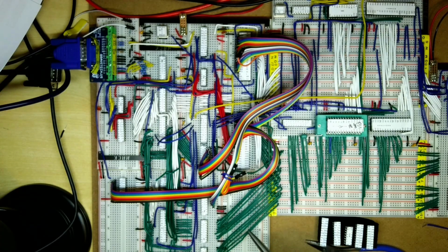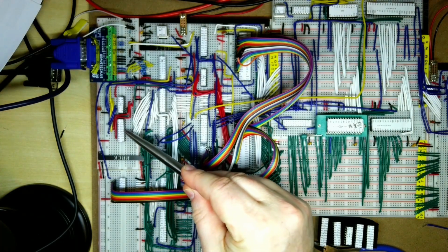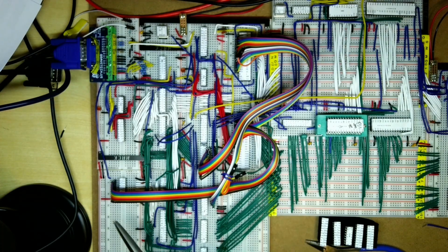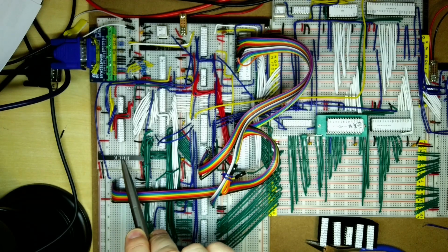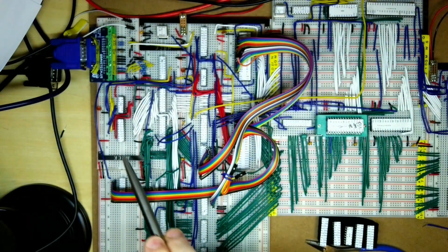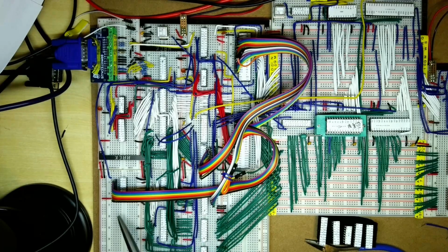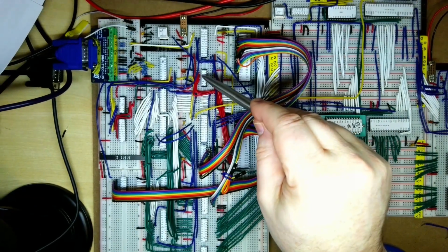So we may need to reroute some of these cables, but we need to rewire these anyway. And then over here we've got the current color latch and the character latch, and I think if we move this bar up to there, then we can fit in the extra latch there, and we can also fit the extra latch in there. Then we just need to wire the outputs of those over to the inputs to the shift register here.